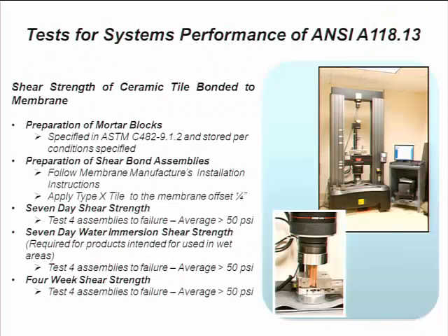One of the other specs relates to the shear bond strength that's developed with the membrane and the mortar. What you're looking at is when you're doing a shear, from a manufacturer's perspective, everything has to be uniform, including these cement blocks that you are testing. Their water absorption has to be the same. Their exterior finish has to be the same so that the tests relate from test to test to test.